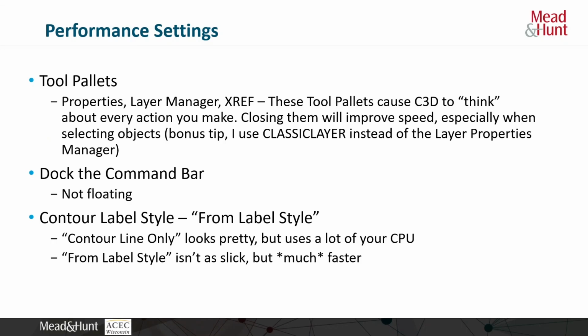I recommend you dock the command bar. Instead of having it float at the bottom in the middle of your screen, or maybe you've moved it up to the top, if it's floating, the text disappears quickly. If it's docked, your text is always readable. I expand my command bar to read generally 4 or 5 lines of text, so if there is an error on the command bar, I can be watching for that and see it when it happens. If I have it floating, then that text may disappear before I notice it.